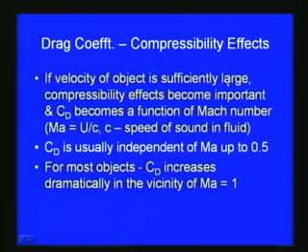Then some other important parameters where the drag force or coefficient of drag changes include the compressibility effect. If the velocity of the object is sufficiently large, then the compressibility effect becomes important and the coefficient of drag becomes a function of the Mach number. Here the Mach number is the important dimensionless parameter. Mach number is equal to u by c, where u is the free stream velocity and c is the speed of sound in the fluid.